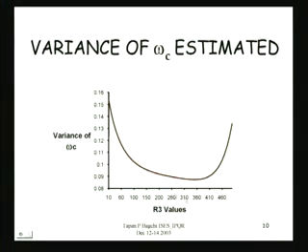So that could be taken for granted. Now all we wanted to do was minimize the variance of omega C, the cutoff frequency, and that could be done by just doing a little search there. We found around an R3 value of 360, we got the best design, the most robust design that gave us the minimum variance. And this variance, of course, was simulated by Monte Carlo.